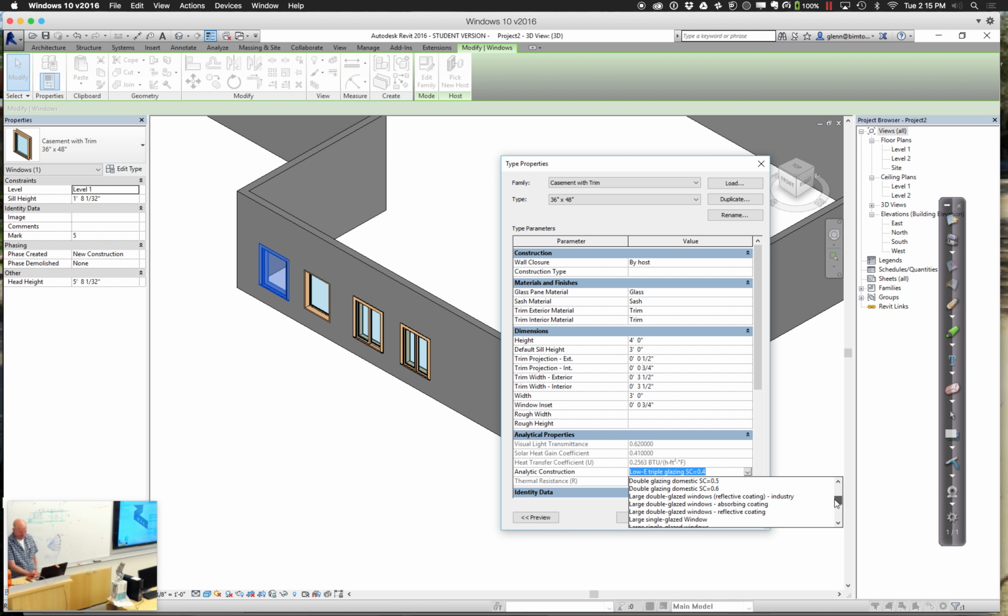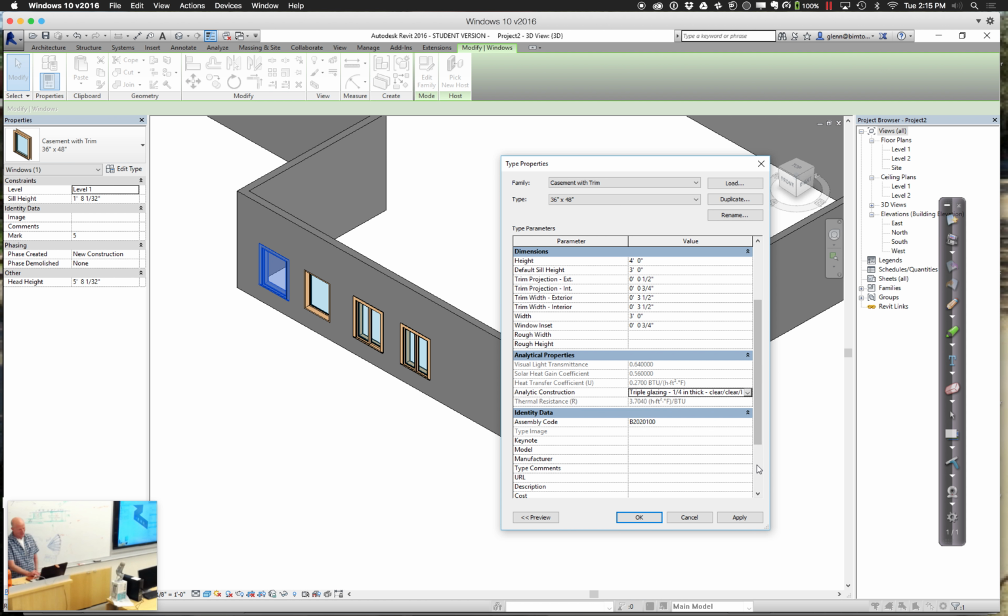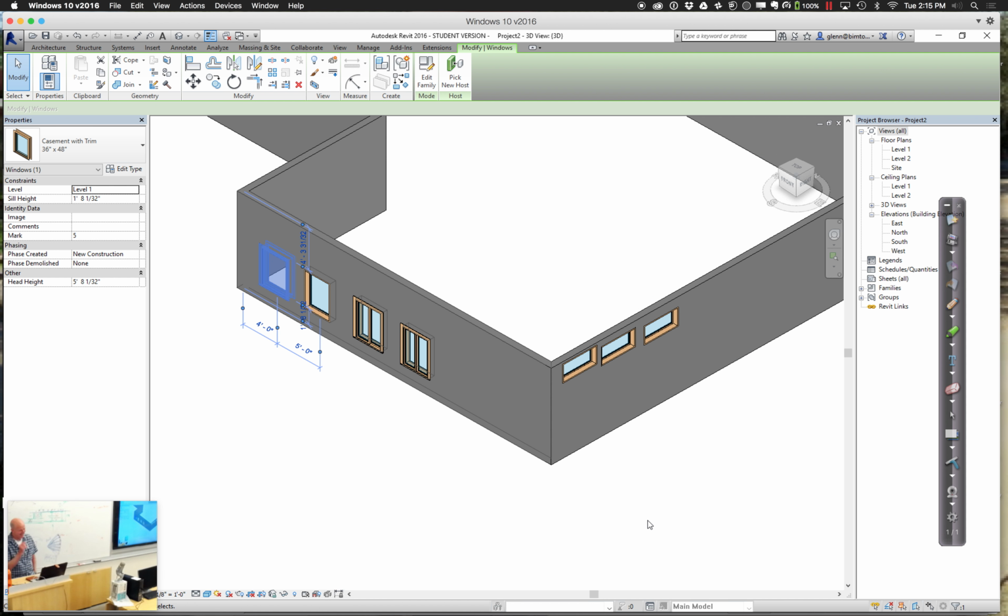An air partition. See how much difference it actually makes to be triple glazed, quarter inch. No, the thickness of the glass doesn't help that much. Okay, so you can go ahead and find different values you want. And ultimately this is all going to factor into the thermal performance. So when you go through and you run thermal performance calculations, let's go ahead and we'll put a little more on this.